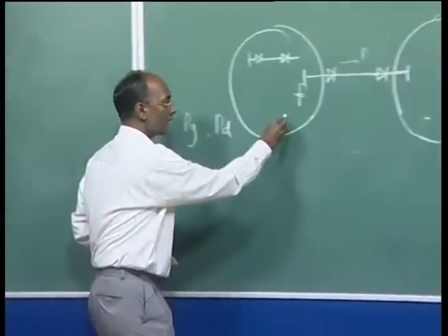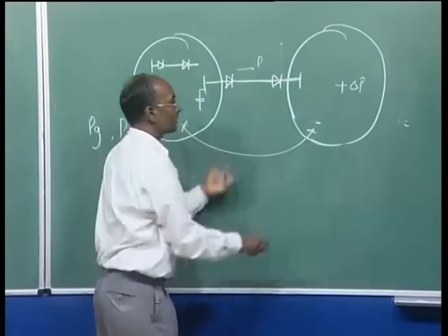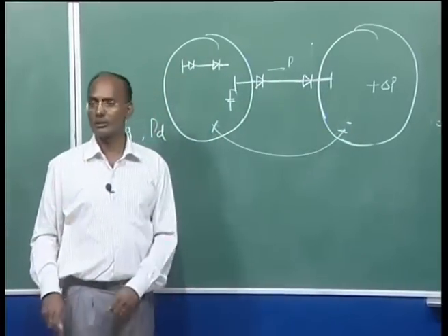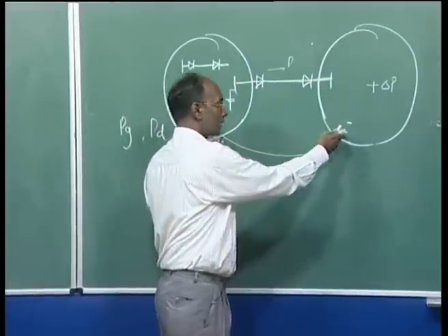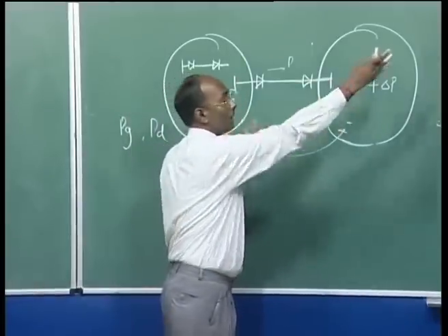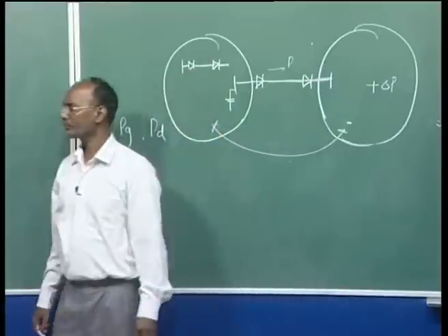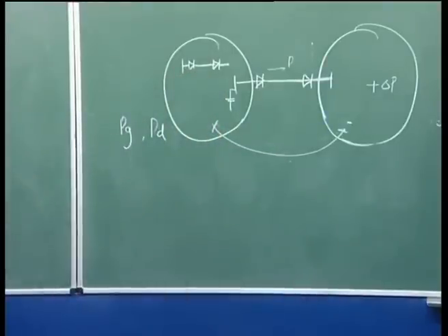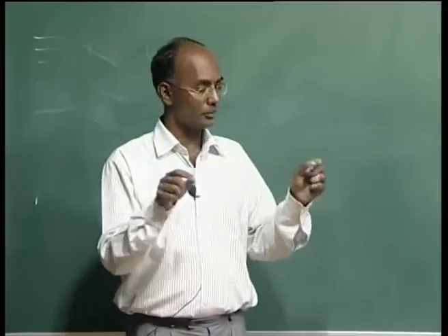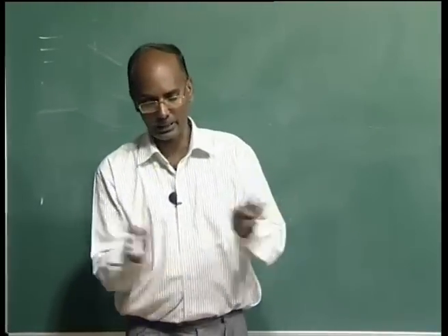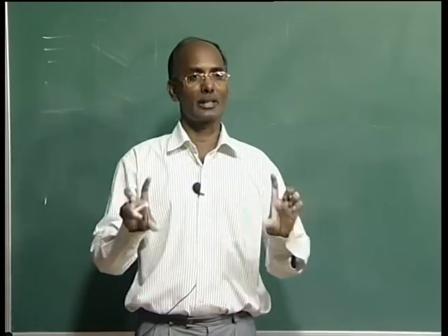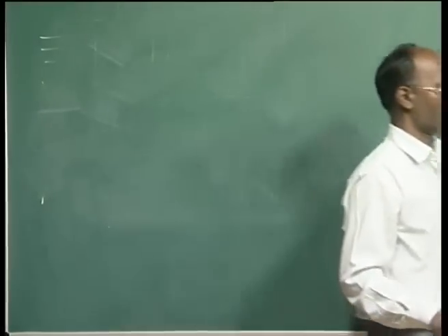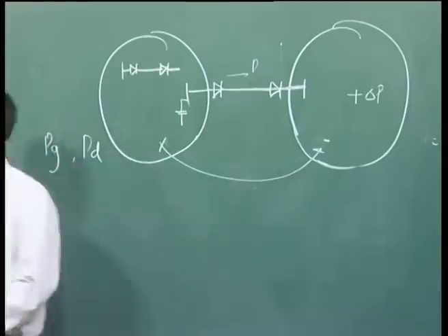Even though these areas are connected by an AC line at some other point, we still want to control somewhere here as well, because this line may sometimes be very weak or a very low voltage connection. Here we require long distance power as well. So tie line power control, no doubt, is one of the major objectives of HVDC. If you have a back-to-back connection, it means one area and another area are controlling each other. Tie line means the two areas are connected, and especially it is a back-to-back connection.